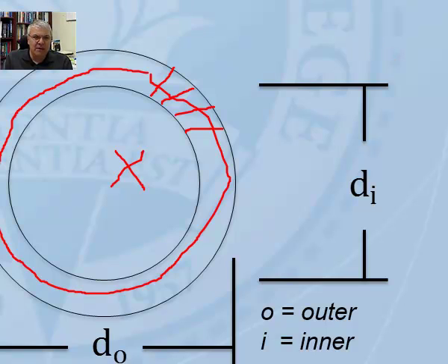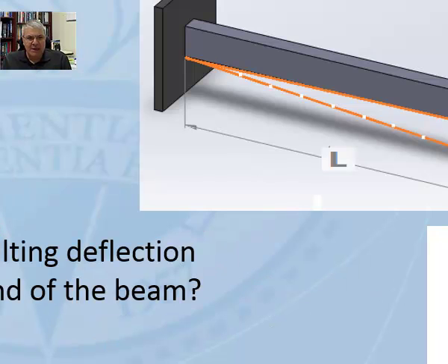So F would be, of course, different now. Again, all you need to do is, in the original F formula that I developed, do the substitution for I, and you're going to have different forces. You can do a little exercise on your own to see which cross section has the least amount of displacement at the tip. You can play with the F that you calculate, and you would see for which cross section you require more force or less force in order to provide the displacement at the end.